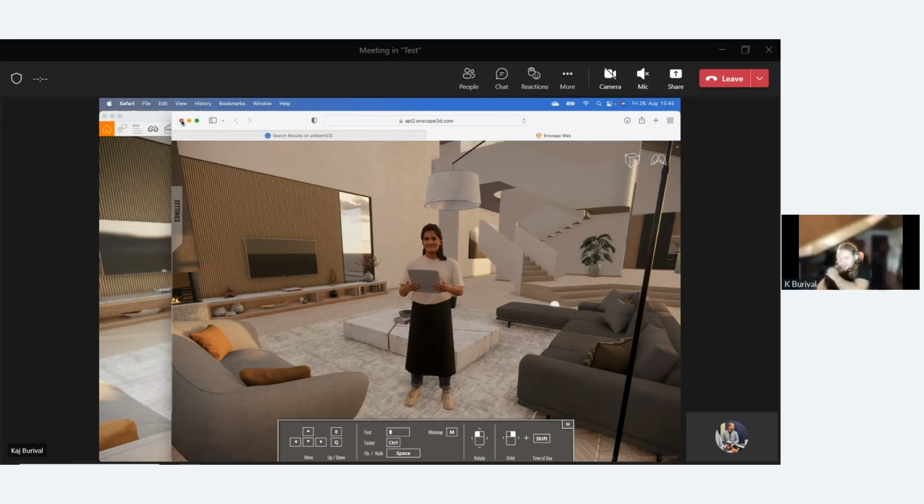Great question. That is something that is already available for Enscape for Windows and should come to Enscape for Mac very soon. We have a custom asset system in Enscape for Windows where you can import models in OBJ, FBX, or GLTF format. And yes, those are being rendered in the same quality. Of course, the assets that we provide, made by our 3D artists, are optimized for real time. So they don't have an overly huge amount of polygons, so you can place a big number of them in your scene. But if you're importing your own models, they will render just as well.